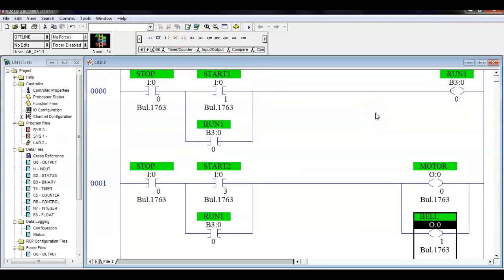So this is the same circuit, but what I've done is we can duplicate inputs. Even though I've got one push button, in motor controls we would have to use multiple contacts. But here we can use the same contact how many times? We can use it as many times as we need, right? You understand? So even though I physically only have one contact hooked up here, now we can do what?